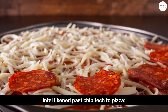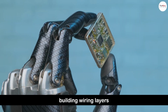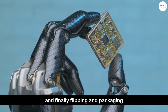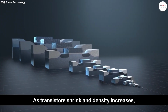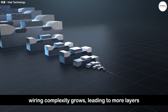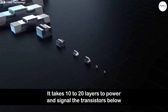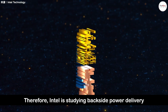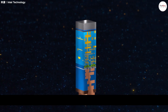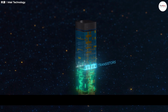Intel likened past chip tech to pizza, layered from the bottom up, starting with transistors, building wiring layers, and finally flipping and packaging. As transistors shrink and density increases, wiring complexity grows, leading to more layers. It takes 10 to 20 layers to power and signal the transistors below. Therefore, Intel is studying backside power delivery, or BSPDN. This tech places interconnects above and below the silicon surface.